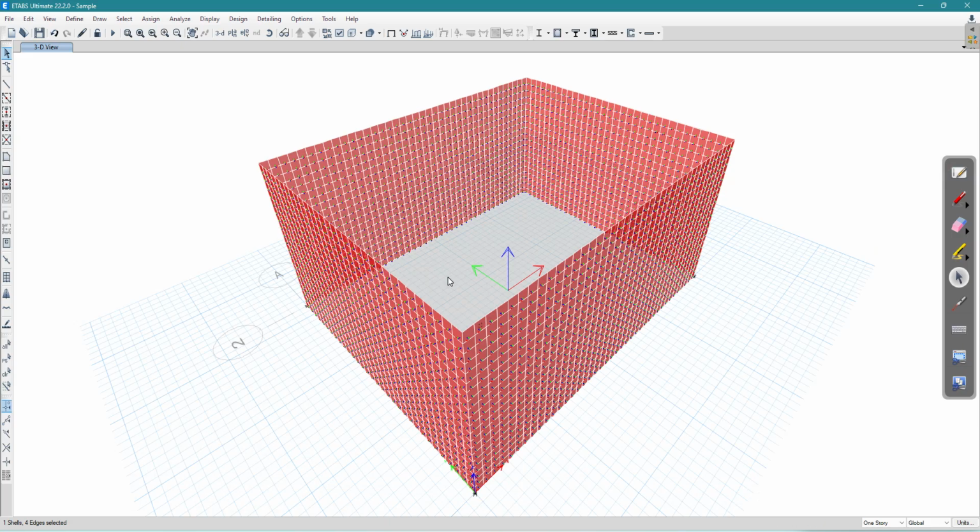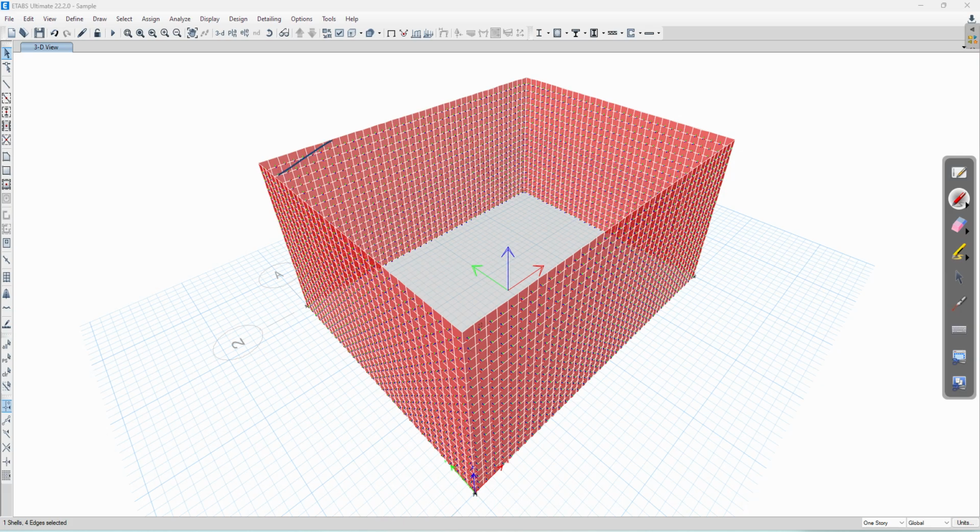See here. So inside the tank, your tank is completely filled with water. So you have taken pressure distribution from top of the tank to bottom. You taken pressure distribution diagram as from this 0, here it is 50, here Z value is 5 meter and here Z value is 0. You taken complete area, or the water is entirely filled, the tank is full.